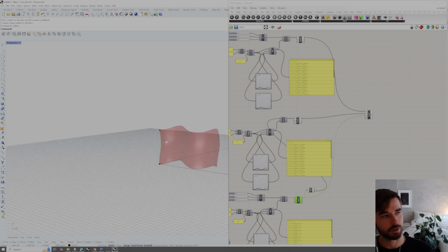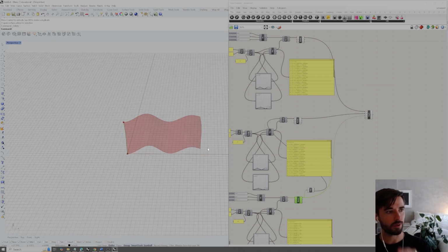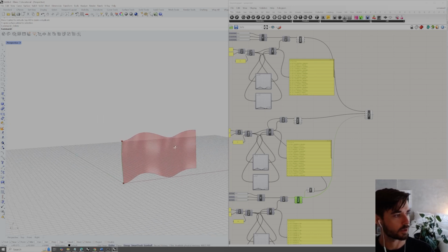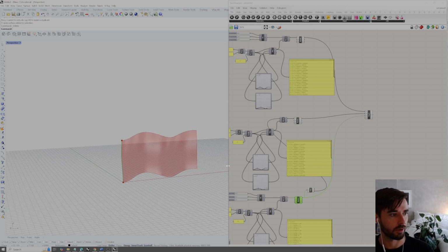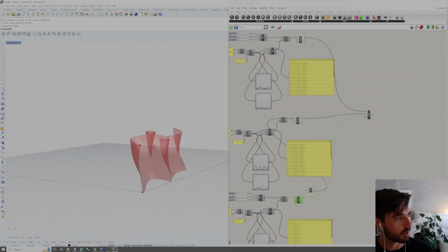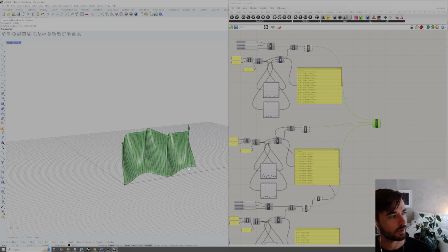And that's a lot cleaner geometry than our previous sweep 1. So by controlling both the top and bottom, we get a lot cleaner sweeping geometry where it avoids that kind of kinking or self-intersection. And we still have the flexibility to make adjustments to this geometry as well. So we can adjust this sweep geometry, and we can change the frequency on the top and bottom. And if we wanted to bake that, we could just select the component, right click off of the component, and bake.